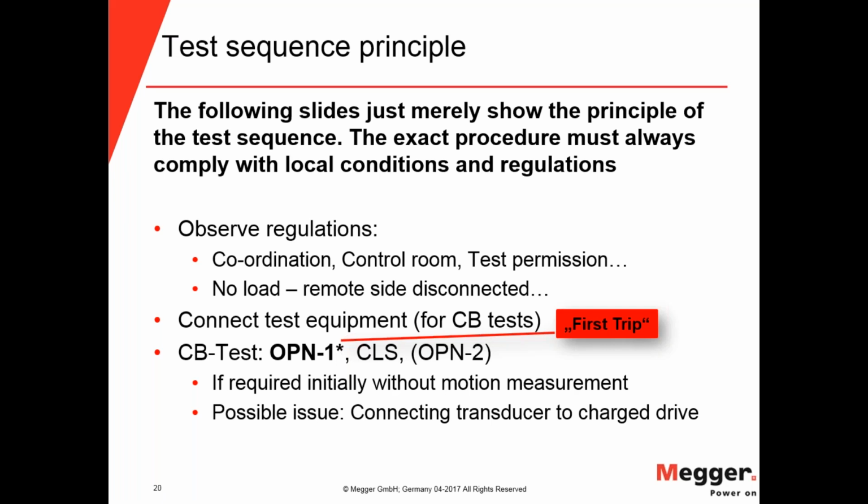And after only 1 or 2 operations, that behavior can be masked, you exercise the breaker, so the behavior disappears. So for that reason, it's important to record this first operation, which in this case you get actually for free with this method, without further arrangements or efforts.